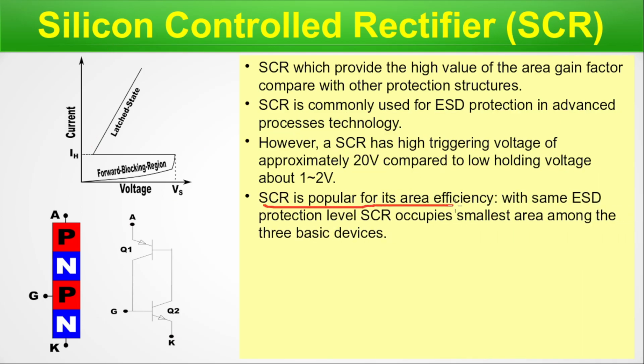SCR is popular for its area efficiency. With the same ESD protection level, SCR occupies the smallest area among the three basic devices. The area efficiency of SCR is very good, and that is what we need because in VLSI we need power, performance and area optimization. We have an entire episode on PPA.